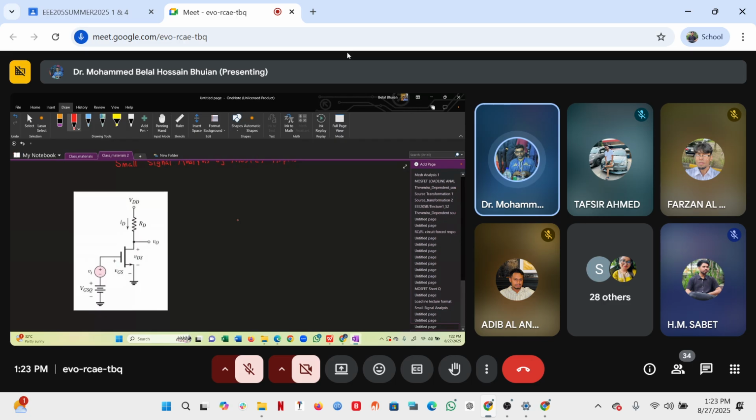Okay, so if I say vGS, it's the instantaneous signal, because the symbol for the voltage is small but the subscript is capital. So it represents VGS plus small signal vgs. It's the large signal VGS and the small signal vgs. So this is our amplifier.